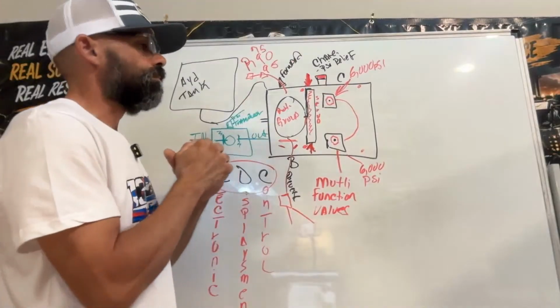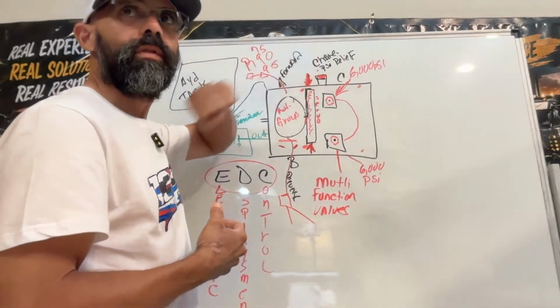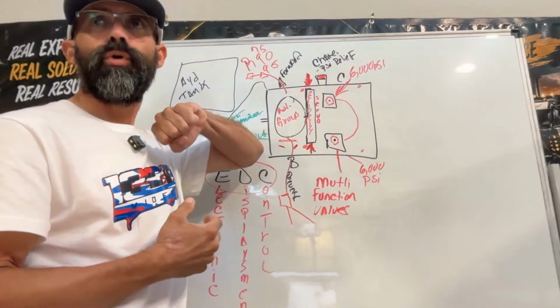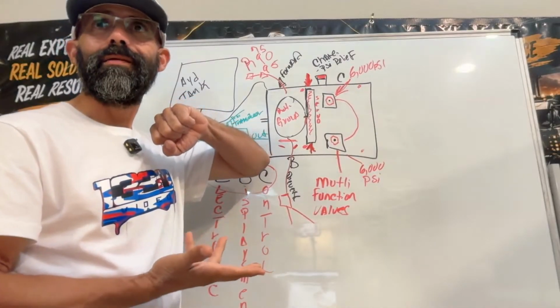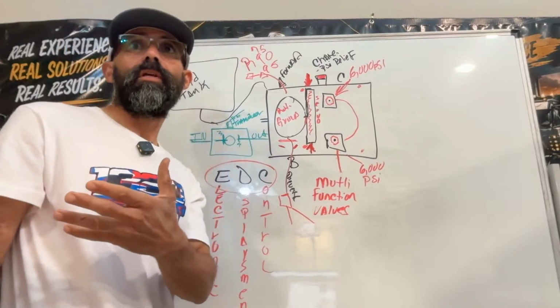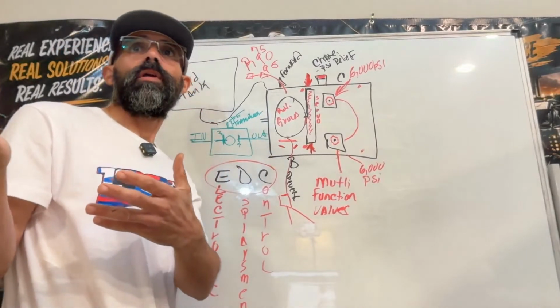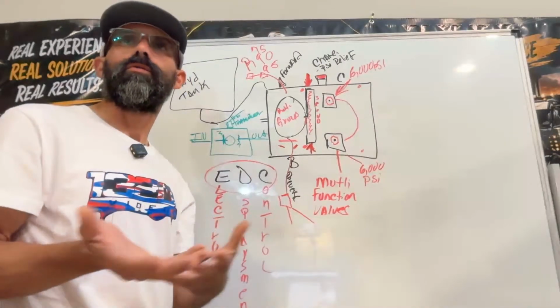So that's why I always like to go straight to the pump with a digital pressure gauge. Digital gauges are precise and not really expensive. You can get really expensive ones, but you can get ones for a reasonable price that will do the same thing.